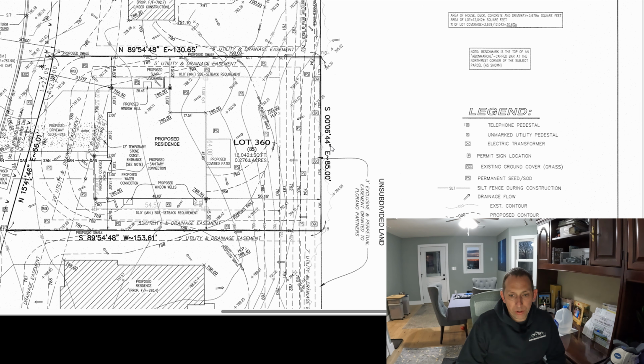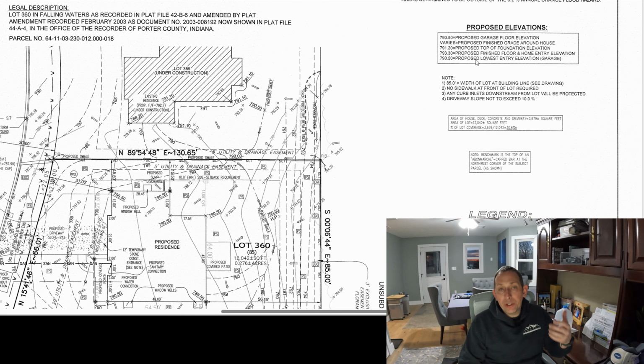And then you see there's all sorts of squiggly lines and solid lines and symbols and signs everywhere. All of these things you're seeing on the screen are called out in the legend. But before I jump down to the legend, because I seem to get ahead of myself sometimes, you need to know where all these elevations are based out of. You need a constant, or your excavators need a constant, and your foundation guys need a constant to know where to set their laser and their transom. So that is what's called the benchmark.